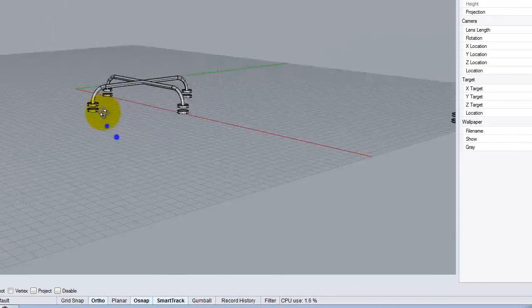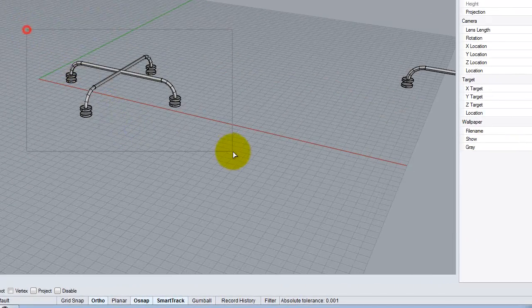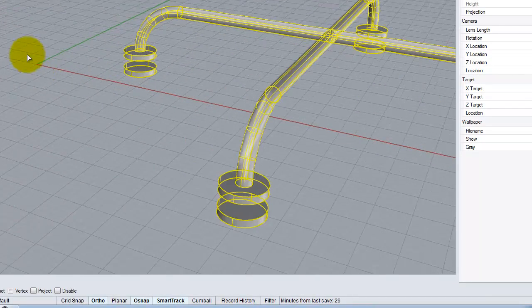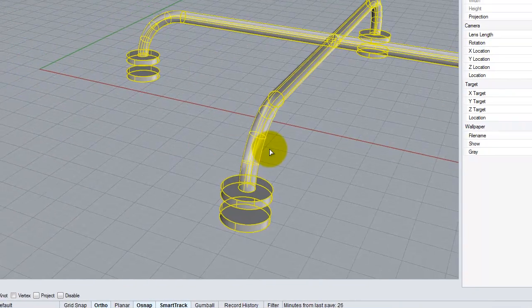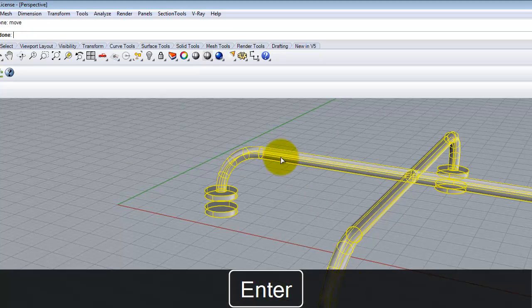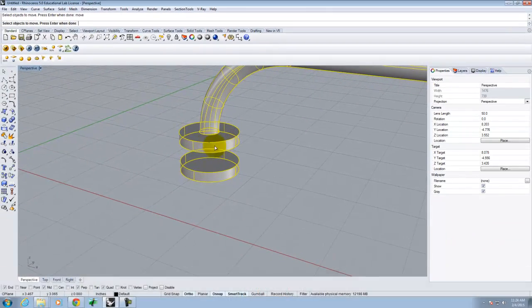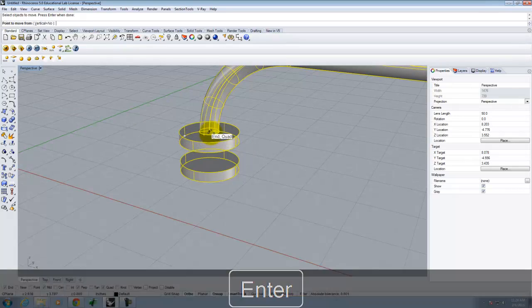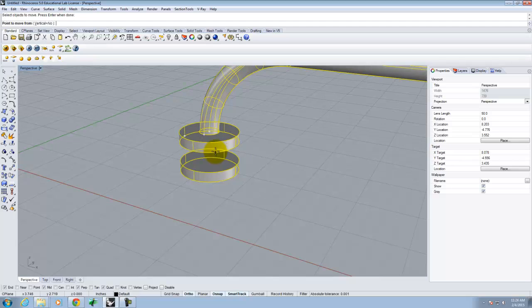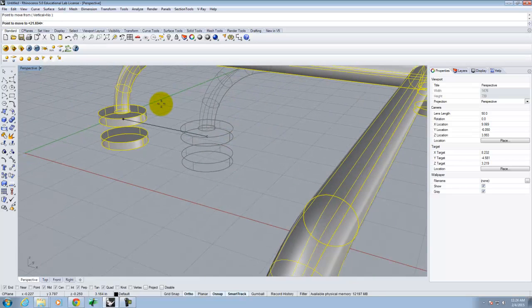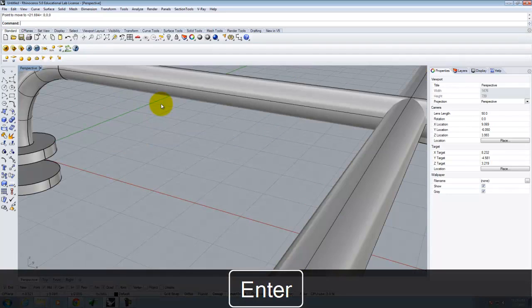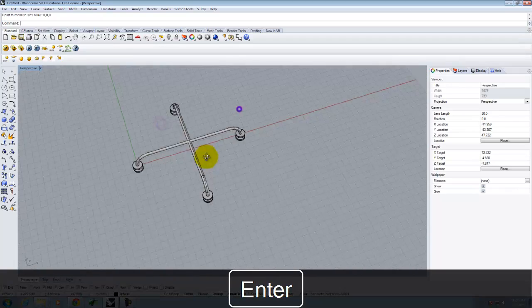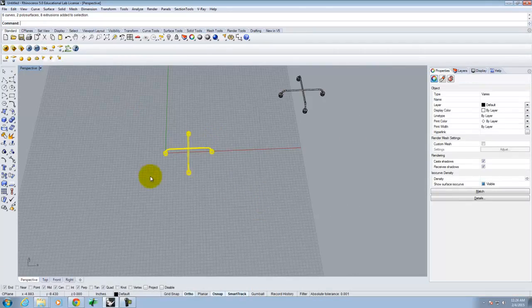So I need to make a few adjustments to this in terms of where it's going to line up. So I'm going to go ahead and select this shape, and I want to move it, because I didn't start right at the origin, I'm going to move it over to the origin. So I'm going to go ahead and say move, and I'd really like to move it such that the inside, instead of the center here, I'd like to be down below. So I'm going to turn on my center snap and snap from the center of that circle, right, the bottom, and I'll put that at 0, 0, 0. Okay, it just makes things a little bit cleaner. Doesn't really matter where it is.